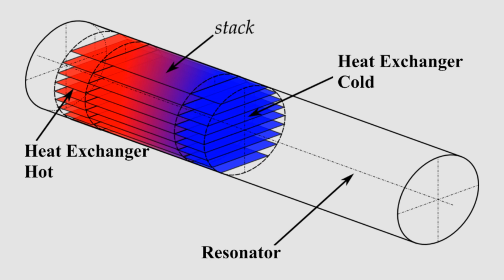It does find use in a slightly modified form where you don't actually have a pump but rather have a vibrating tube. It's called thermoacoustic cooling. This is used in very low temperature but long duration freezing processes, as in cryogenic labs, for example. You basically have a tube and air in it, and the device itself is kind of a fringe case. It's kind of a solid state device, but not really. It does move, but it doesn't really have moving parts. It just vibrates elastically.